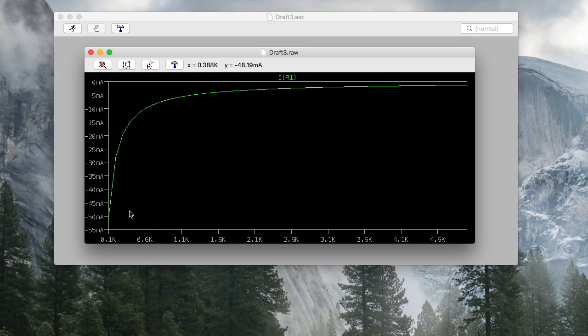Now don't worry about directionality here. It says negative, but that's because of the reverse way I did the circuit. So what we're going to look at here is you'll see there's 35 milliamps at the bottom all the way to the top. The higher the resistor, the lower the current; the lower the resistance, the further left you go, the more current. So we're going to pick somewhere around the middle, anywhere from, I would say, 6 to 15. So you'll see that ends up being a value. If you look at the top as I scroll through this, it's telling you the resistance.